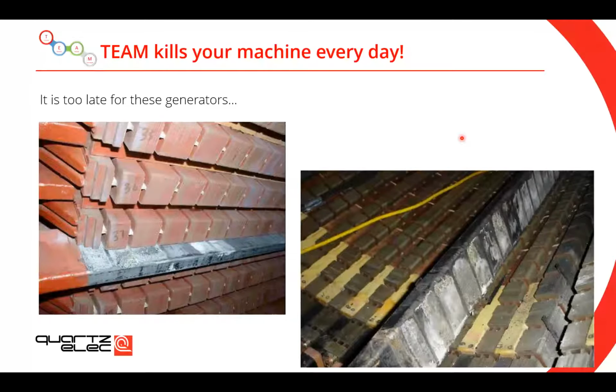So yeah, I think at the end we can all agree that the stresses kill your machine every day. Again, just two examples of machines and generators. And for those two machines, it's already too late. These two machines have signs of very high partial discharge activity on the surface of the stator bars, and these operators ended up having a stator rewind.